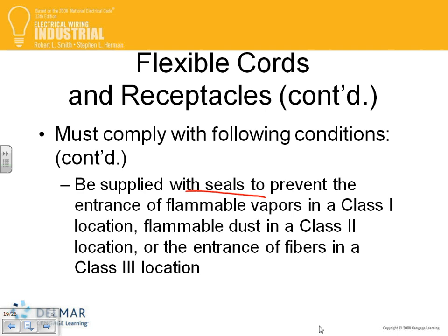But can I use a cord? Yes. Not to wire, just to tie to equipment. Here's my question for you guys. Can I use a flexible metal conduit to tie to an air handling unit or a chiller? I hate to use that, or a motor in a Class 1 Div 1 location? Yes, they can make explosion-proof flexible metal conduits or liquid tight or whatever you need, but we can't use it to wire. We can only use it to tie to equipment.